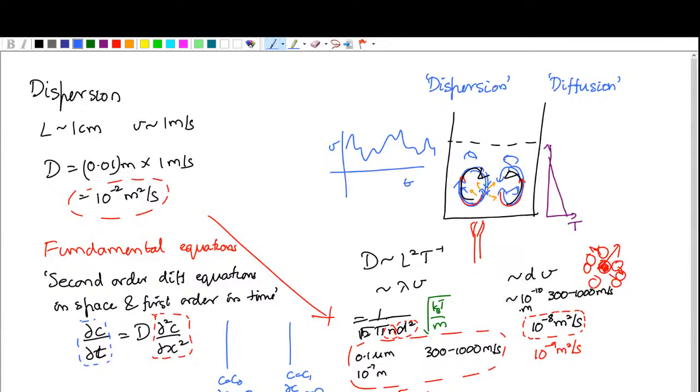And for momentum transfer, the velocity has to be 0 because of the no-slip condition at the walls. So typically the velocity at the wall for a solid surface will be 0 because the fluid velocity and the solid velocity have to be equal at the wall. So you'd have a no-slip condition, which means that at the walls the velocity is equal to 0. And if you have some impeller or something that is rotating the fluid, then on the surface of the impeller, the velocity of the fluid is equal to the velocity of the impeller itself. Okay, so that will be the boundary condition for the momentum exerted on the flow.